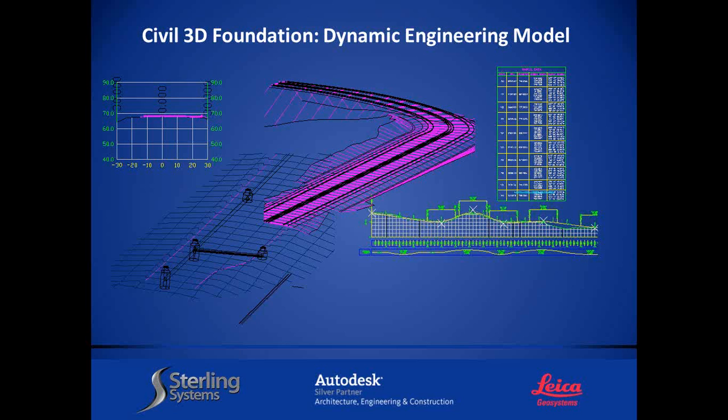The first part I want to introduce is any type of road design that we're going to get into later. You typically have a surface, you have your 2D road design, your alignment, then you develop a profile, and you sample existing ground and design the new road. Then you have a typical section that you run along that road to create the engineering model. We call that a corridor in Civil 3D, and that's what you see in the center of the screen here. If you move the horizontal alignment or the vertical alignment, this automatically updates.